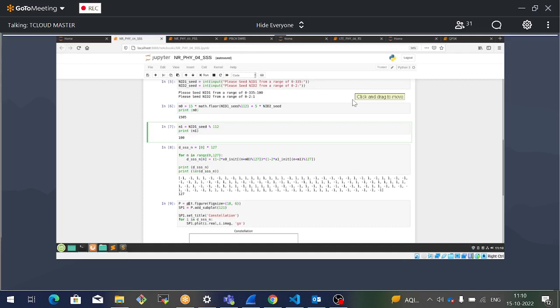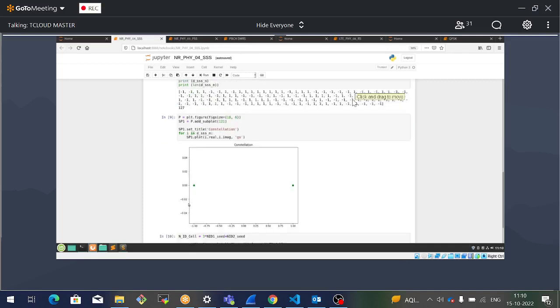So you get this. And if you draw the DSSS, even this is a special symbol set containing only ones and minus ones. The symbols in the constellation are either on the right hand side of the origin or the left hand side of the origin without any angle, at 0 degrees or 180 degrees.